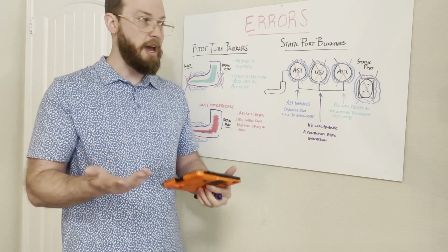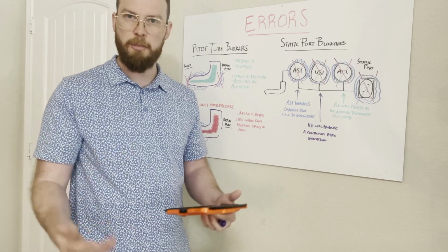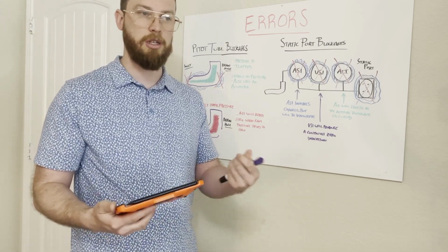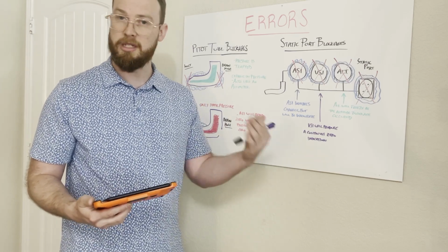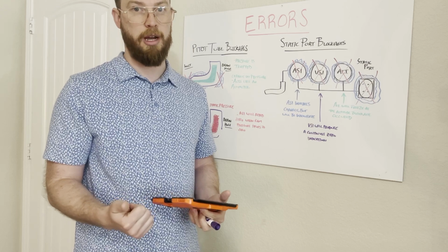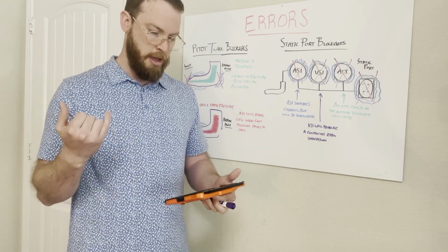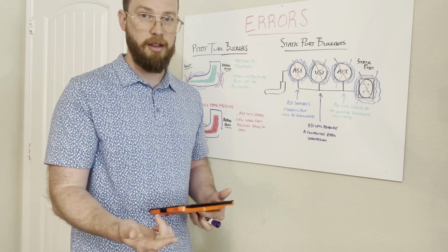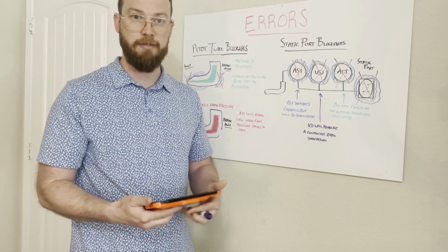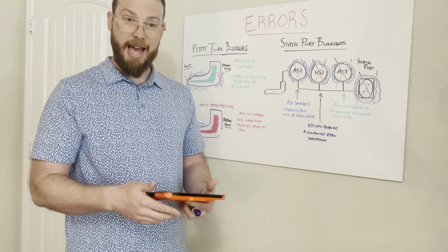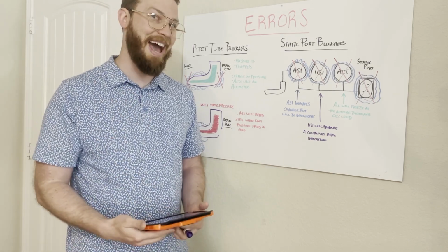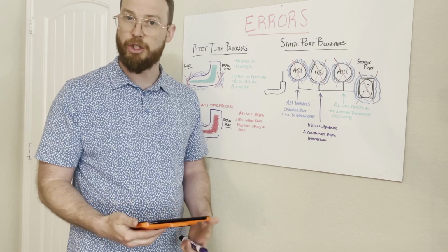So if we suspect something like this, and if we get caught in heavy precipitation or flying IFR and don't really realize until it's pretty late that our pitot tube and static port is frozen over, we need to turn off autopilot if we're using autopilot, hand fly, and make sure our pitot heat is turned on to melt some of the ice if it's iced over. Exit the icing conditions as quick as we can. So climbing or descending, getting out of that icing condition area.